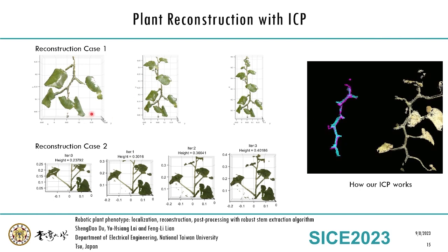And then the robotic manipulator starts to reconstruct the entire point cloud. Because of the error from camera or environment, registration is needed. This GIF shows how the iterative closest point, or ICP, method works. Two cases show that the method could perfectly register two point clouds.